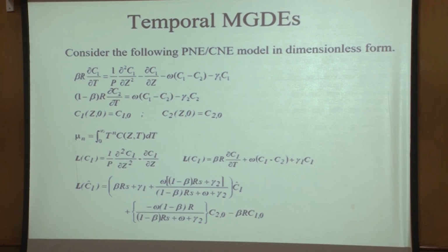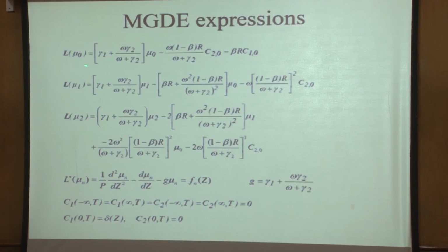All these s terms will vanish, and we will get an equation like this, which is the governing differential equation for how the 0th moment is going to be evolving in space, because over here we have del square with respect to z, or del with respect to z. So basically, as I keep changing my location along the column, this tells me how the 0th moment is going to change for whatever flux is crossing that location.